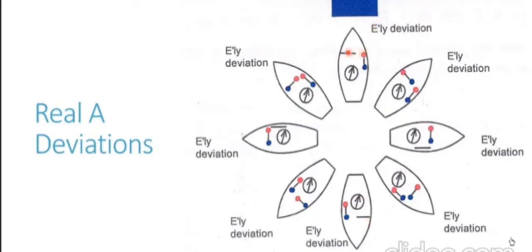Now the magnetic field lines are going vertically upwards. If you concentrate your attention on the athwartship beam, this beam is not aligned in the direction of the magnetic field. It is at right angles to the magnetic field of the earth. As I told you in induced magnetism, there is minimum, zero or negligible induction when the soft iron structure is misaligned with the inducing field. The inducing field is in the north-south orientation, and this athwartship beam is in the east-west orientation. The vessel is heading north, so the beam is in east-west orientation.